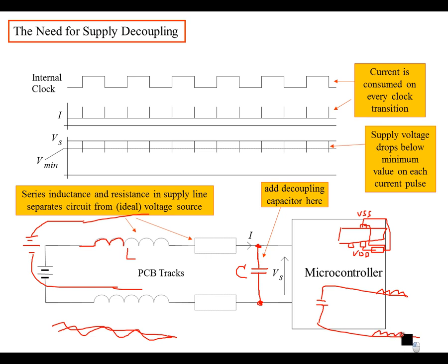And remember, inductors and capacitors are opposites of each other, corollaries of each other mathematically, so any series inductance is going to cancel capacitance. In that case, you're going to just null out the effect of your decoupling capacitor. Okay, so these are your decoupling capacitors.